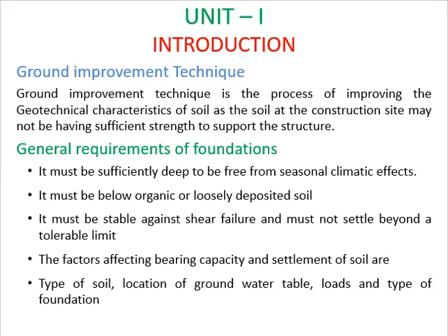As we know, the structure of a building is divided into 2 components, superstructure and substructure. The superstructure is the part of the structure which is above the ground level and receives the live load. The substructure is the supporting structure which transmits the loads of the superstructure to the ground. The purpose of the foundation is to distribute the load over a large area so as to bring the intensity of load within the safe bearing capacity of soil.